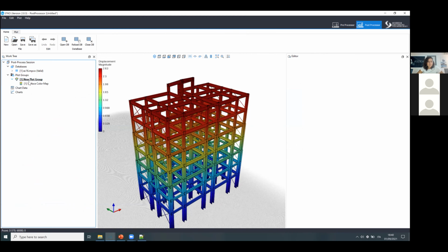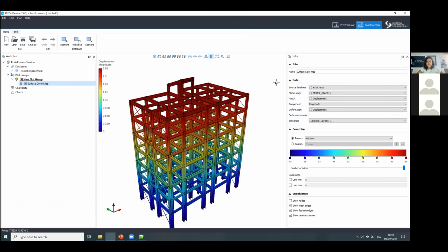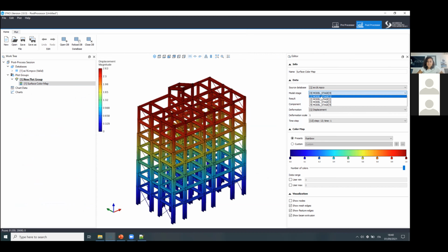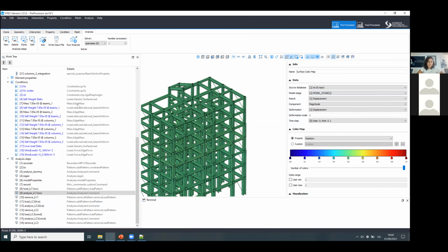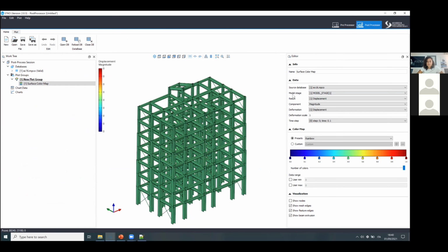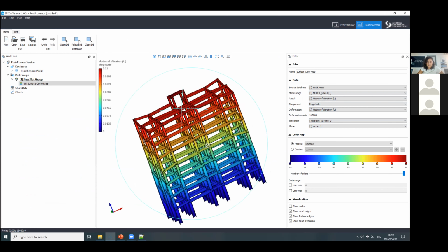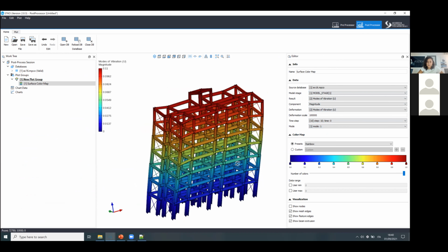As you can see in the results here, you have numerous model stages. Model stage 1 is the one we defined initially for the eigenvalue analysis. Once we input the record here, this creates a model stage for the information up to this point. So in the first model stage, we have our modes of vibration results. So we plot them, we check everything works as expected, the model is all connected and is moving together.